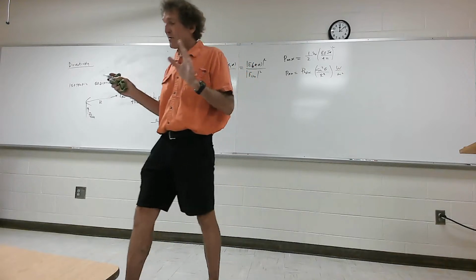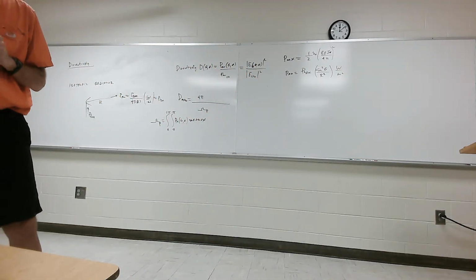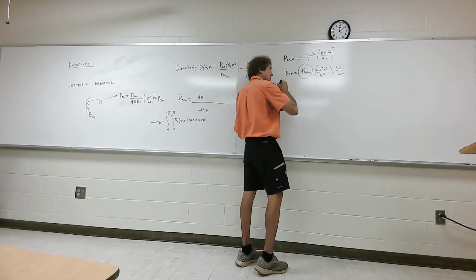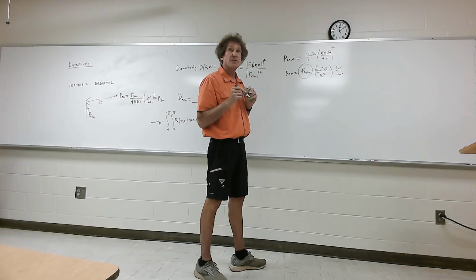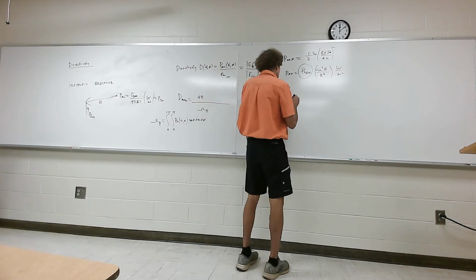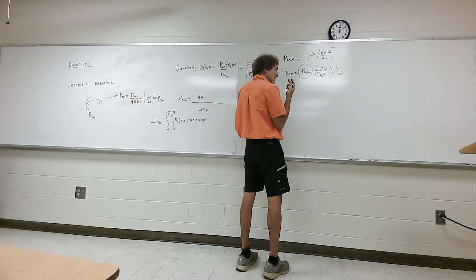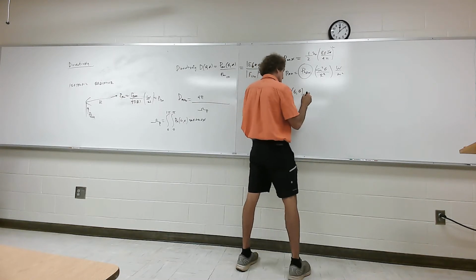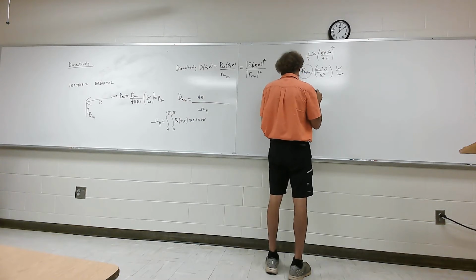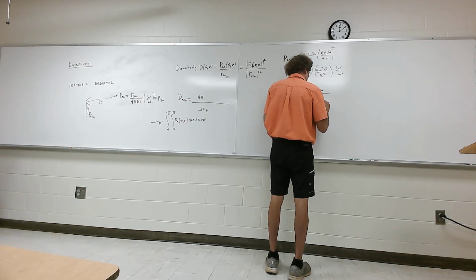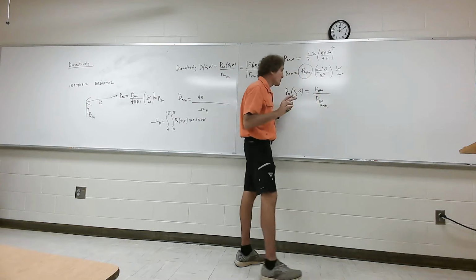You're going to forget about R. It will not be a function of radius. The only thing you do is find a maximum value of this, which happens to be P max, how convenient. Then you divide it into the actual power density. So when I take a look at the normal, this is called the normalized power density. It's a function of both theta and phi possibly. What that is going to be is the actual power density divided by the maximum power density, P max, at a given R. Now R will always go away.